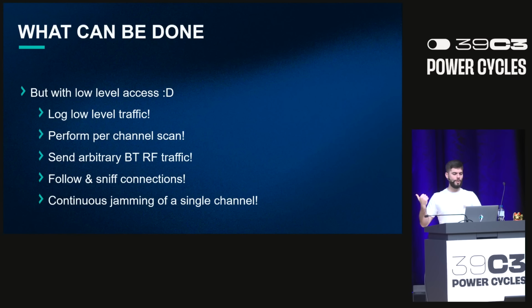Such as in other projects, we will be able to follow and sniff connections that we can see happening. So for example, if we see a connection packet start, we can take the parameters from the connection and just follow that connection and dump the traffic. And there's this mechanism which allows us to receive packets with a certain level of bit error on them. So we could theoretically receive some traffic of which we do not know the synchronization word which will be in this connection packet. So a partial sniffing can be made.